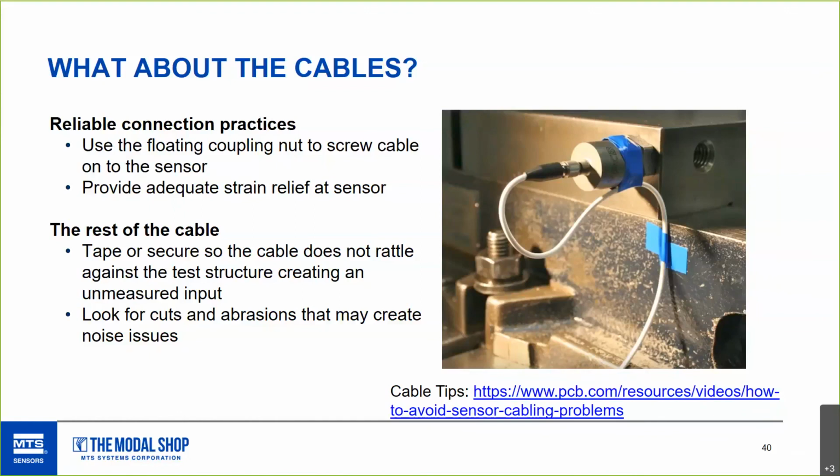But tape your structure so it doesn't rattle and you're not measuring something undesired. Look for any cuts and abrasions on the cable. Often cables are put away at the last minute, and not enough attention is paid to the poor cable. Anything else you wanted to say? No, I mean they're kind of your last thought, but your first problem when you don't get a signal that seems correct. And again, there is a cable tips link there that we'll also include.